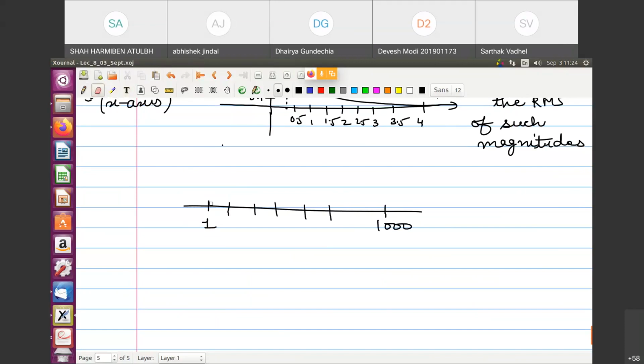Just draw it on the y-axis. So your quantization error will increase a lot if you are using uniform quantization. Let us say on the y-axis is the sample value, 1 is the minimum, and 1000 is the maximum, which is when some person is very loud and shouts. So let us say the amplitude is 1000.